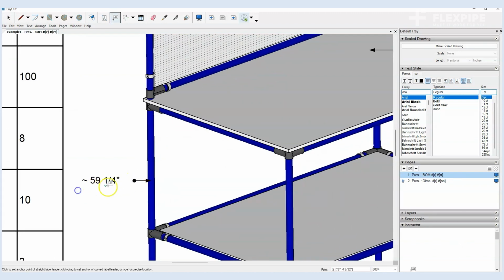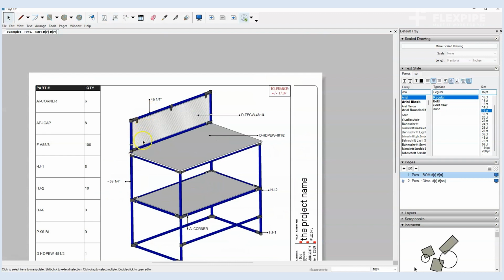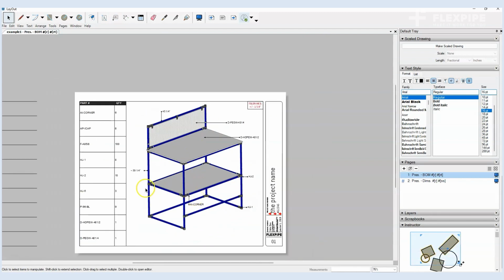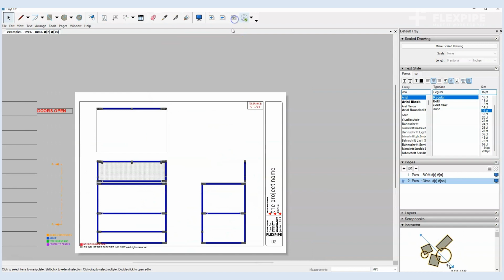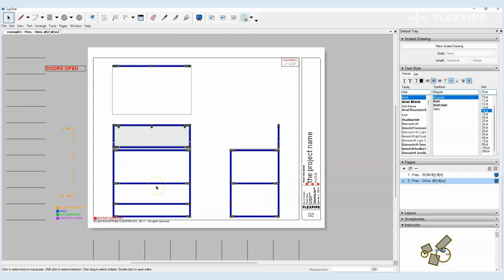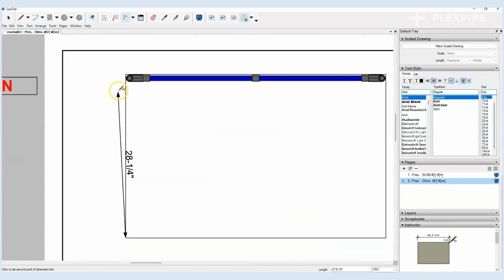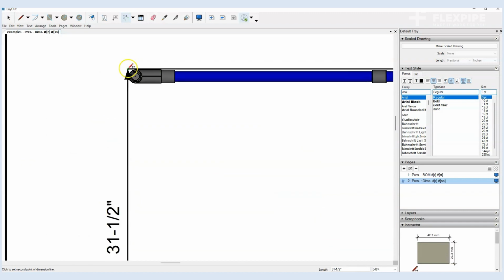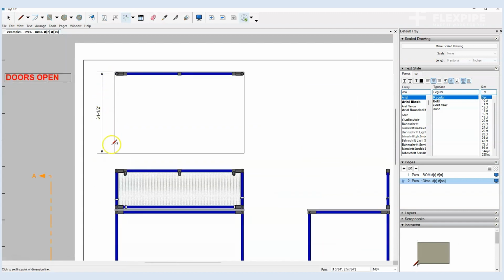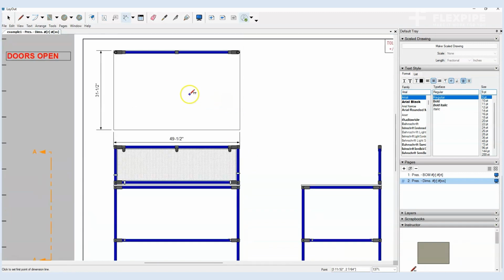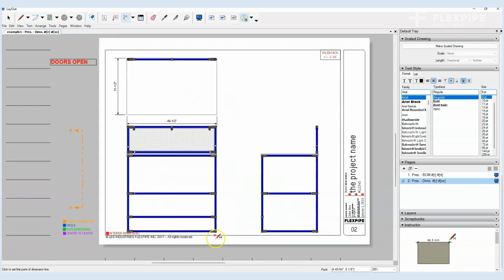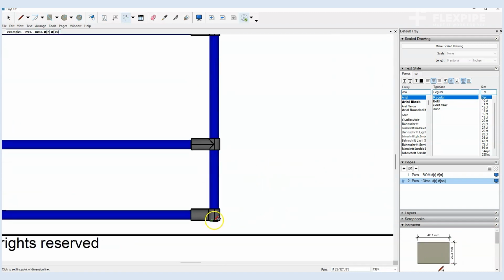This is a presentation drawing, so we don't want to have too much information. We just want enough information to be able to see the project and what it's all about. So in this case, for page 2, we can also begin to add dimensions. We can now look at the different dimensions here, and we can see again it's a front, top, and right side view. This is the very basic way of understanding information in these technical drawings. So with all this, we can dimension all of that relevant information.